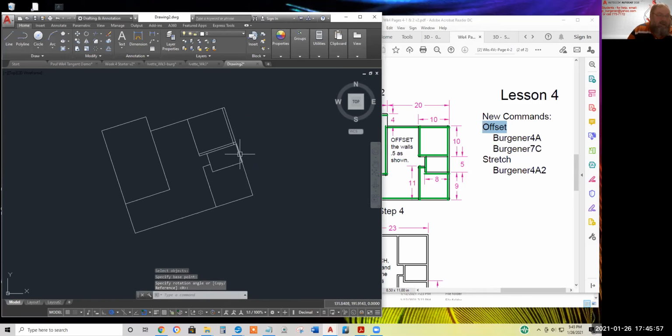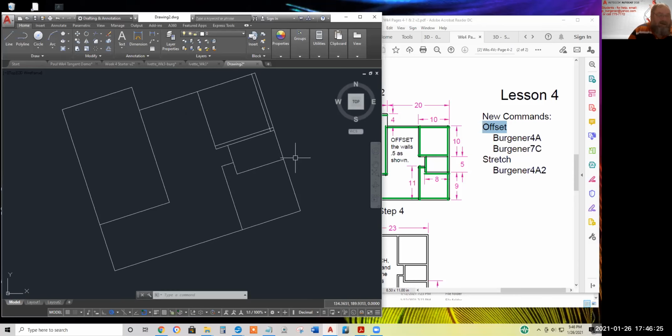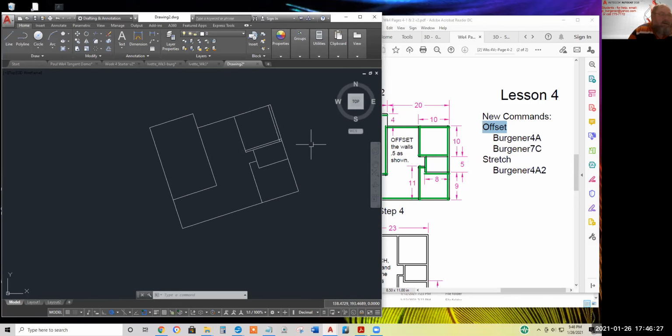Now to place a copy, I'd have to draw a line in space here and snap it perpendicular, and then use the copy command with the intersection here as the base point, snap at the end of that perpendicular line and type the distance I want it to copy. So it copies parallel. A lot of work, a lot of construction line garbage. So again, I'll undo this.